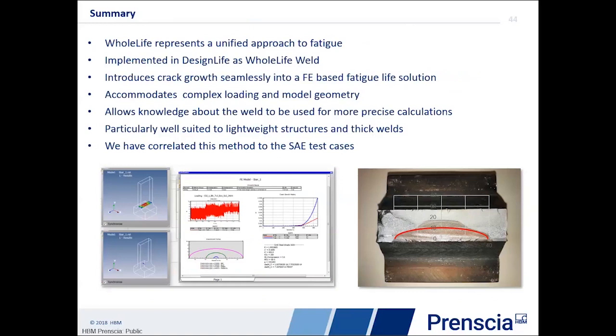And the way we have done this, it allows us to do crack growth very seamlessly inside a finite element-based solution. It handles both complex loading, so I have multi-axial loading coming in, as well as complex material geometry. It allows us to use the knowledge we have about our weld to improve the prediction.